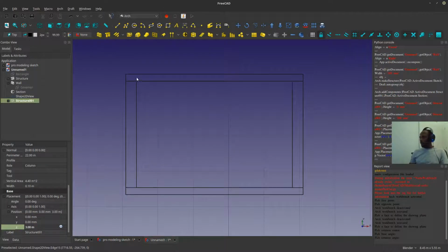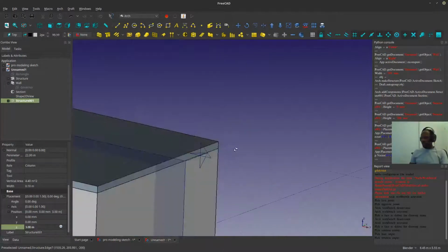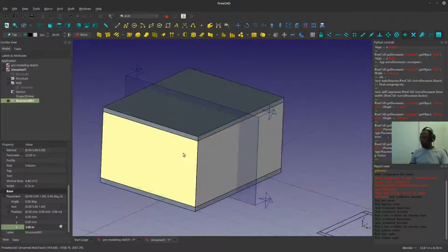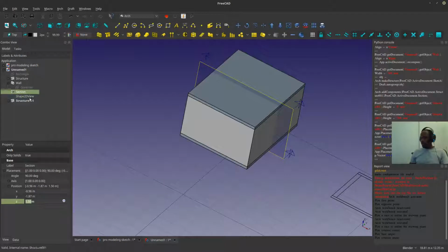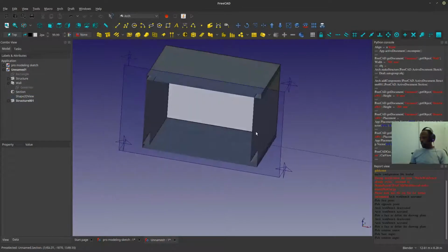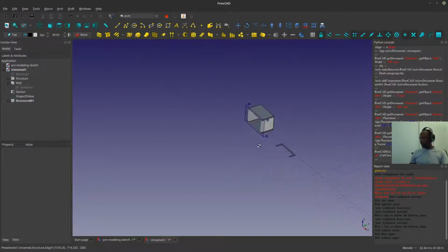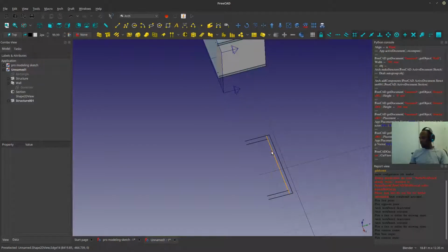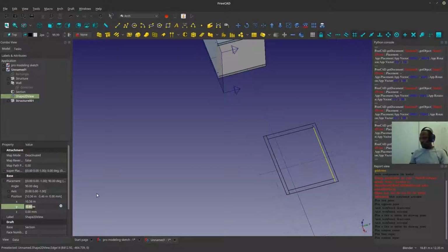So in the meantime, the 3D is just naturally updating itself as well, so I can also be using the 3D to generate these things as I want. So I want to maybe, let's say, cut view true. Okay, so this is my cut view. So maybe you don't like this view, I don't know. Oh wow, it's cutting here as well. So let's move this guy a little bit up on the X. So right here, okay, that's good enough.